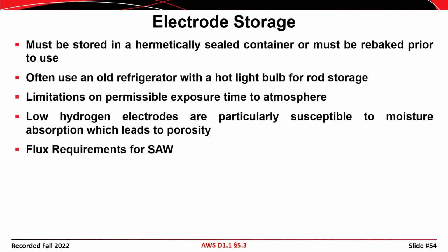Okay, it's important to store the electrodes properly, especially if you have an electrode with the flux that's exposed. If you have just regular shielded metal arc welding electrodes, stick welds, welding rod, for example, and you leave those out in an unsealed container, then the flux tends to absorb moisture. And if that happens, then you might end up with impurities in the weld.